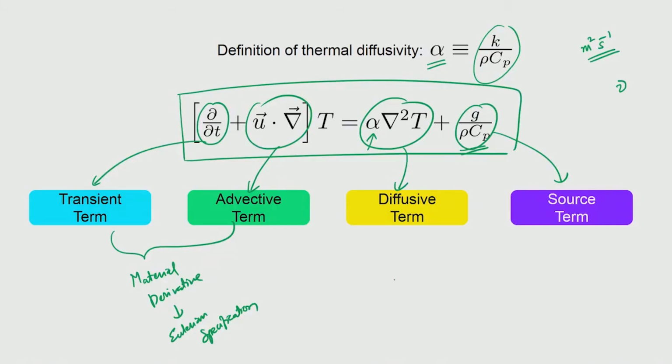This equation has another name. You could also call it the so-called convective diffusive equation. And this basically means that these two terms are being taken into account, and so in mathematical literature, what people refer to as the convective diffusive equation is nothing but this generalized equation that we have written, which falls into a template into which the Navier-Stokes equation or the generalized heat transfer equation can also be cast. So, it is a very broad template that is widely used.